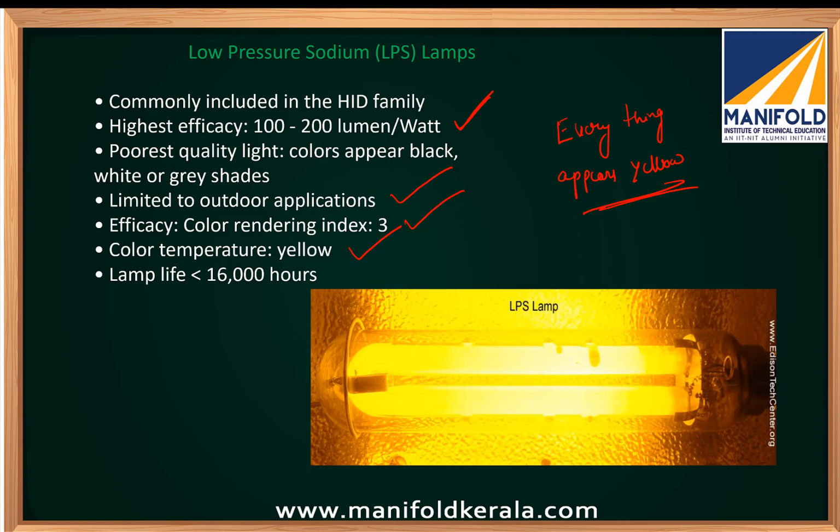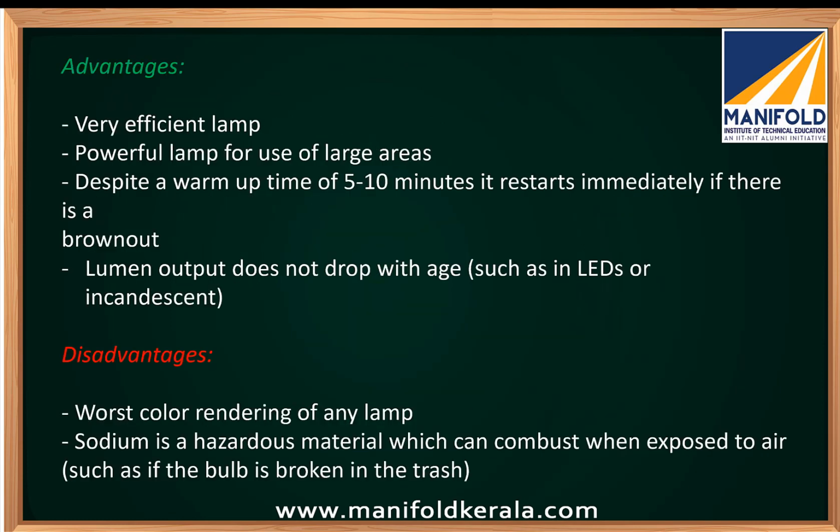And the advantage of this one is it has the highest luminous efficiency or luminous efficacy. Understand? It is a very efficient lamp, a powerful lamp for use in large areas. Despite a warm up time of 5 to 10 minutes, it restarts immediately if there is a burnout. Suppose suddenly because of a power outage the lamp has stopped, you can immediately restart it. And lumens output does not drop with age, unlike LED or incandescent. The luminous efficacy will not change with the aging of the lamp.